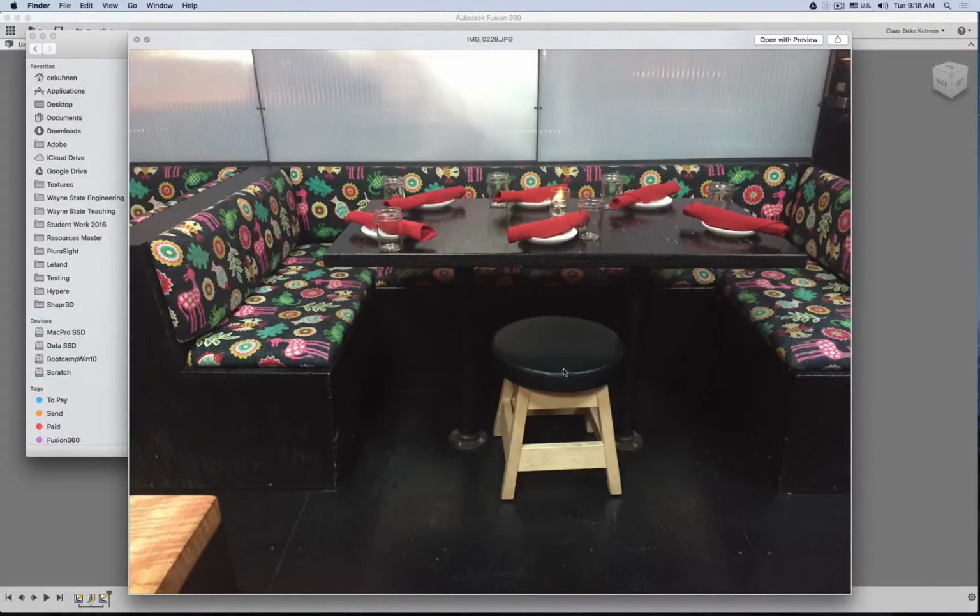So we could maybe say this is 40 centimeters. The height is maybe 46 centimeters. Let's assume 8 centimeters for the upholstery thickness, including the wooden board the wood construction is mounted actually onto. So we have a height of 46 minus 8, so 32 height is for the legs.